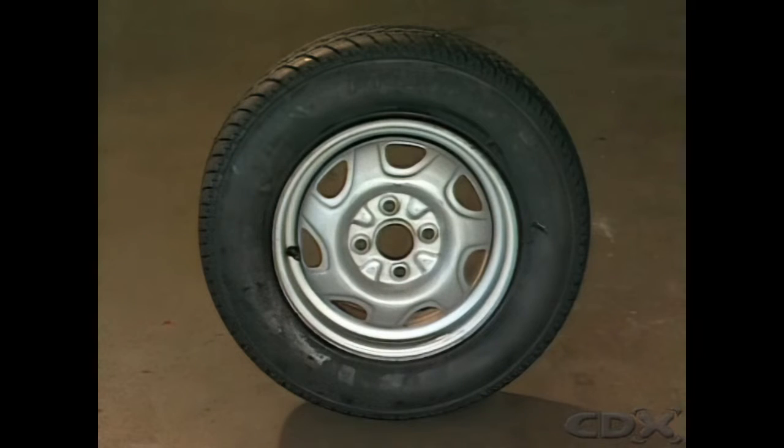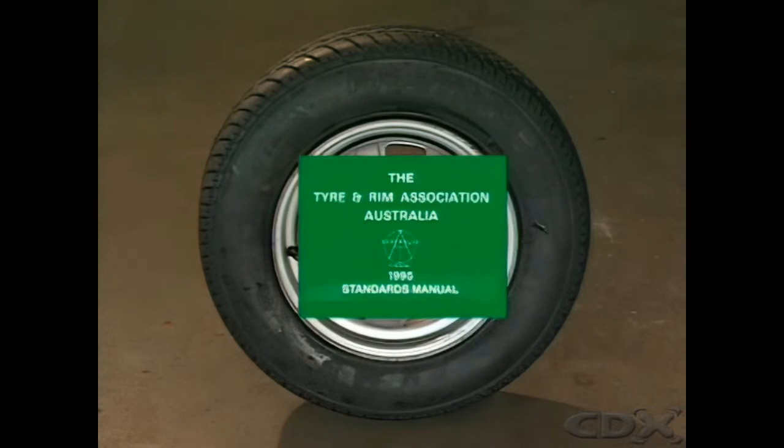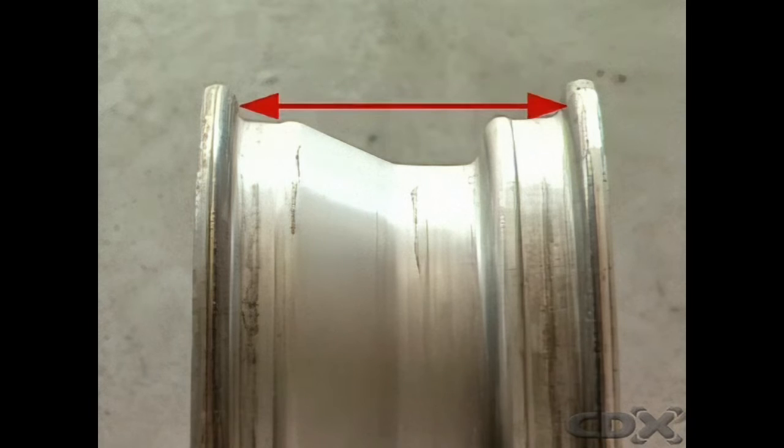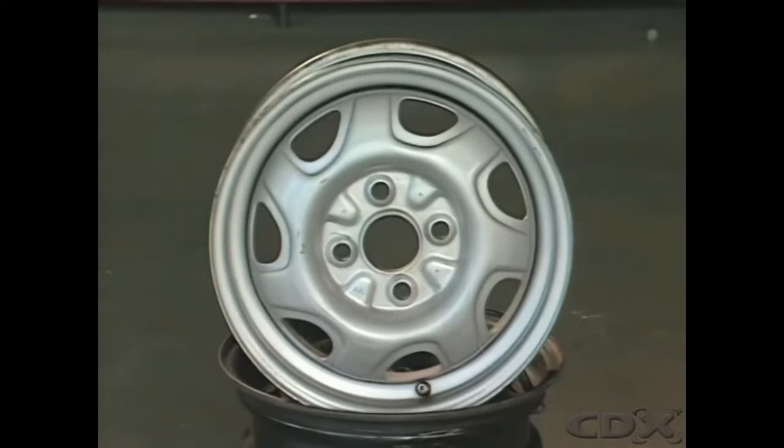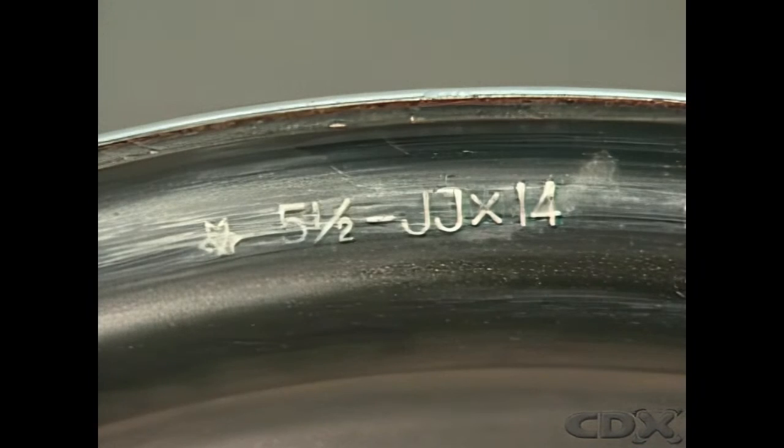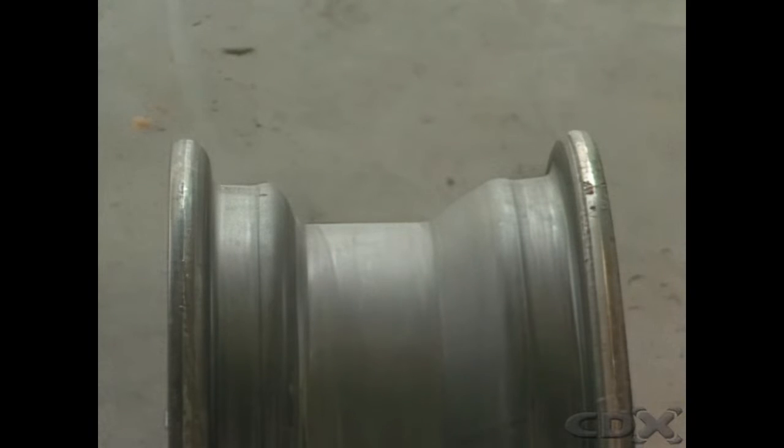To ensure correct fit between a tire and rim, all manufacturers of wheels and tires comply with standard dimensions, as recommended by tire and rim associations. The width of the rim is the distance across the rim flanges at the bead seat. Its diameter is the distance across the center of the rim from bead seat to bead seat. The shape of well-based rims is provided by a letter code, such as J, K, JJ, KK. The width of the rim and the diameter is traditionally stated in inches.